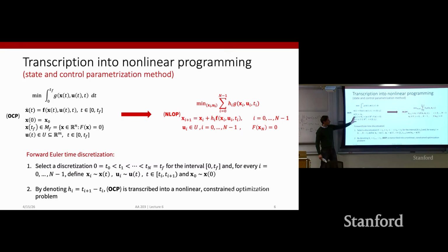In order to do this step from continuous time to discrete time, we select a time discretization, meaning we discretize time from t0 to tn according to some time interval, which we pick. And then for all of our time steps, t0 through tn, which now are just indices, we assume what is called a zero order hold on our control, namely that the control between Ti and Ti plus 1 is equal to Ui. So we assume that the control is fixed in between a single time interval.